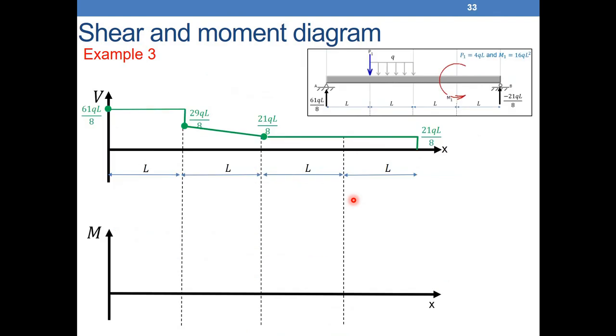Now let's find the bending moment diagram. Now after we found the shear force, we need to keep this always in mind. So let's say where we will start here. Do we have any moment applied around A here? No. Directly around A? No. So here we start from 0. After that, between 0 and here, I don't have any external moment. Until getting to the point here, I will not have any external point moment. So I don't have any point moment around A.